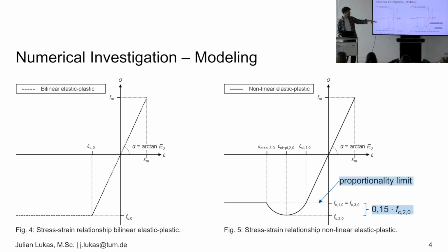For example, the difference here for spruce and also for beech is around 15%. That's what I meant earlier with the 85% when the proportionality limit is reached. We have around 42% one time for the plastic strain, which is like when we take 42% from the elastic part, we add it on the plastic part here and then again. So we have a really long way to go with our element here.